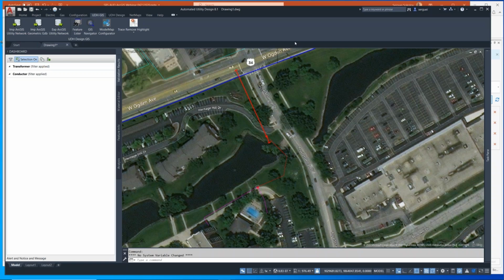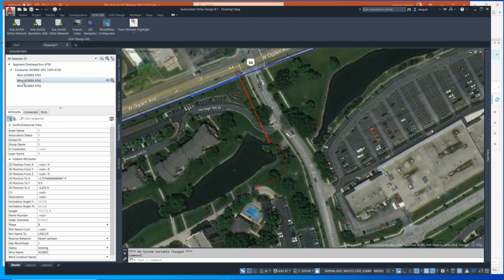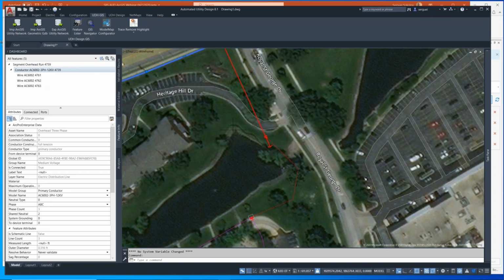We have the ability to pull from geometric network and post to utility network. When we do our transformations on the import, we have the ability to augment data. So in general, out of the box, when AUD pulls in a pole, it doesn't just pull in the GIS information, it also augments that data with pole model data so that we know how strong the pole is and what the max moment analysis is.